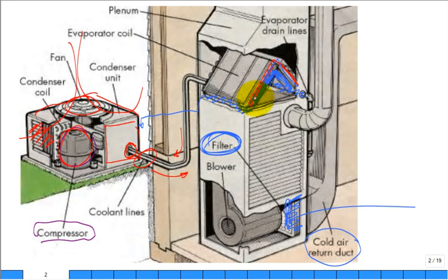And that'll be a cheap one, instead of a $6 filter every month or a $10 filter. Or you can get a really good filter, maybe run for 3 months, 6 months even, on a very deep pleated filter. Anyway, change your air filters.